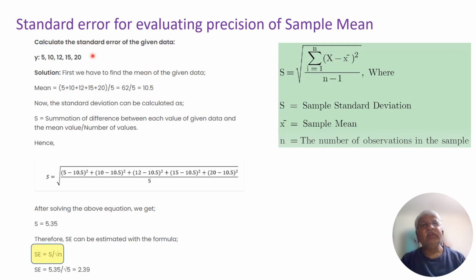So that is how, even in the earlier situation, when we are picking up the sample values for the FFG corner, there is one precondition: its last value, the 3 sigma value, should coincide with the FFG corner. Aside from that, the standard deviation error should also be low. Based on these points, we will get the FFG corner value. Similarly, SSG corner values can also be computed.